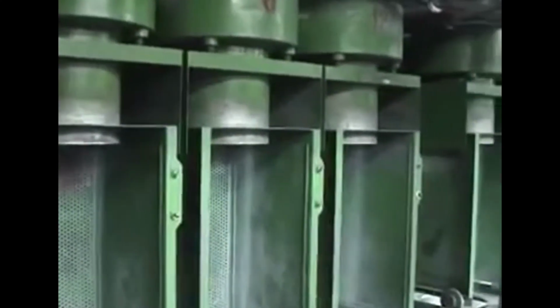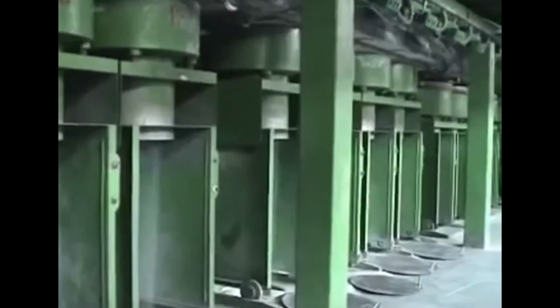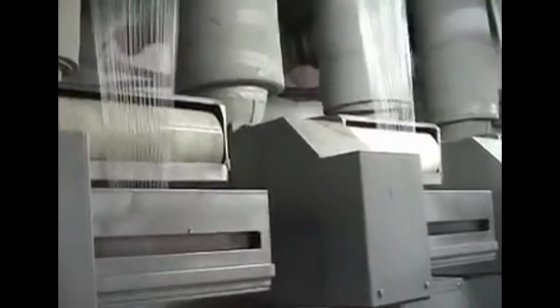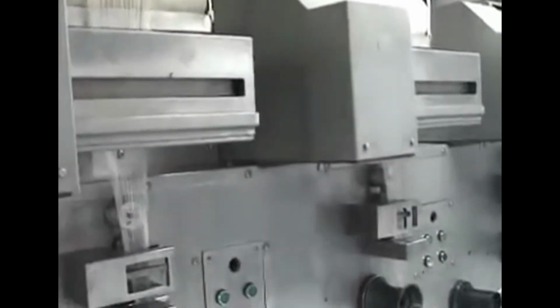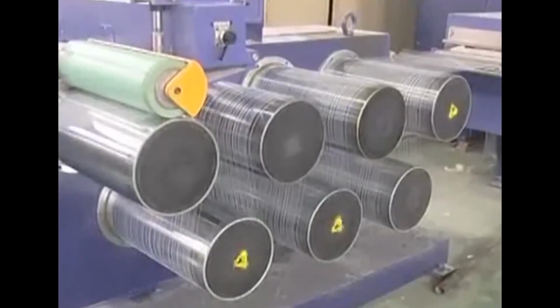So, from the holes of the spinneret, it comes out in thin form and it becomes a filament. It gets solidified by hitting the air. And when you check, that particular filament will not contain alignment of the molecular chains. And these molecular chains need to be aligned to the fiber axis in order to make it stronger.